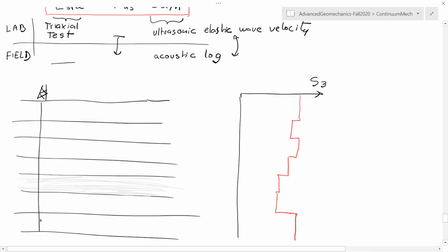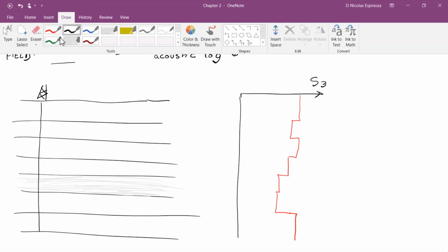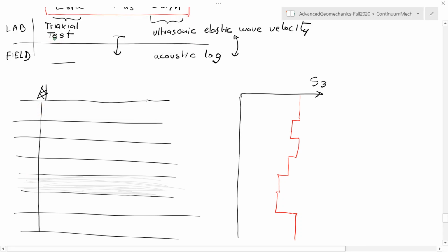According to my model on the right, if I start a perforation here, very likely this fracture is going to start growing in this direction out of the plane, and it is going to propagate down because it finds a lower stress at that location, and eventually growing out of the plane it is going to look something like that.